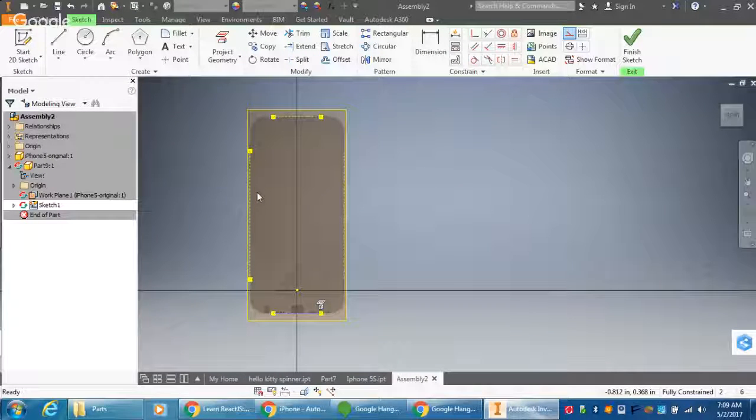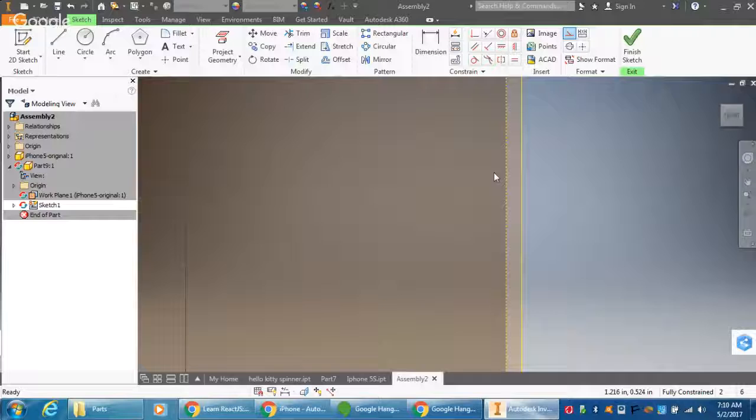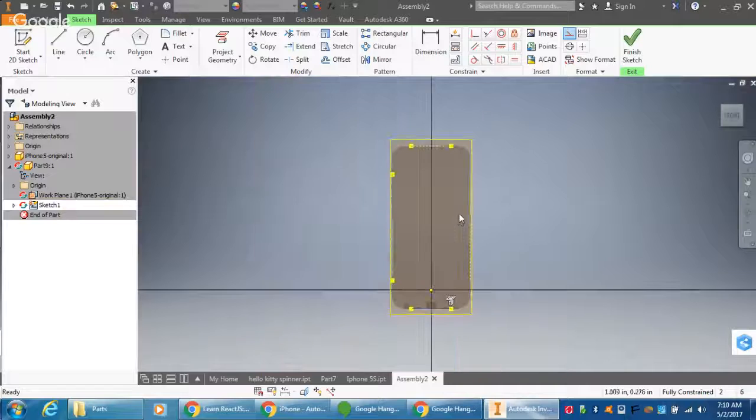Now, our case thickness needs to be between 50 and 100 thousandths. Why 50 and 100 thousandths? Well, I've printed hundreds and hundreds of these, so I can tell you that that's really the best balance between material thickness, how long it takes to print, and how flexible these are so they don't snap when you put them on the phone or do any damage to your phone. So 50 is on the thinner side, 100 thousandths on the thicker side, so you can split the difference if you like. If you just want to do a quick model to see if it fits, I would just go 50 thousandths, but know that that's going to be thin. Not only that, if your phone has little cutouts in it, it's going to snap in place. I'm going to show you what I mean after we move on with this.